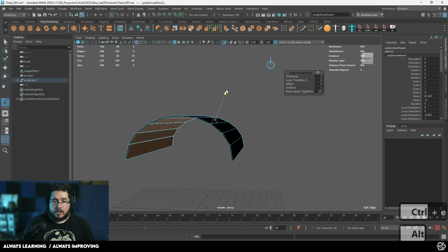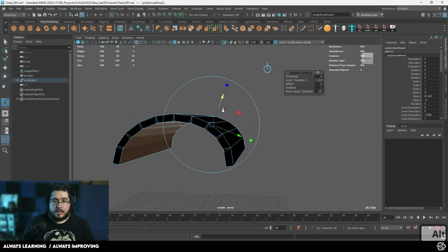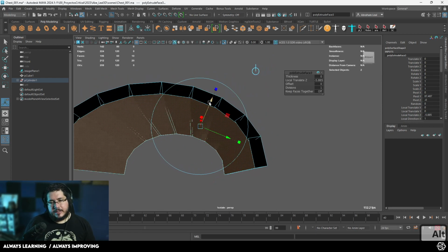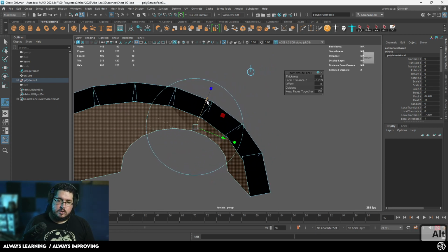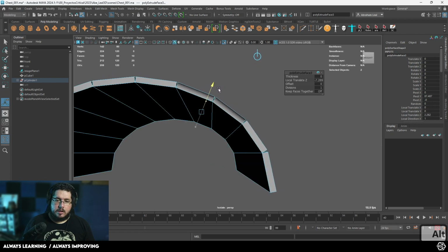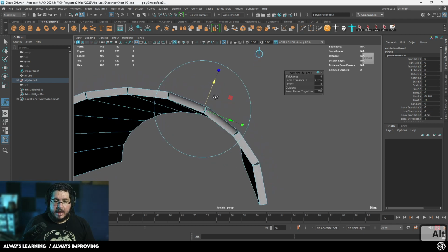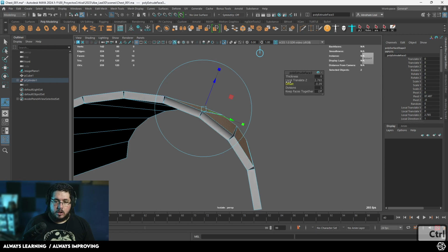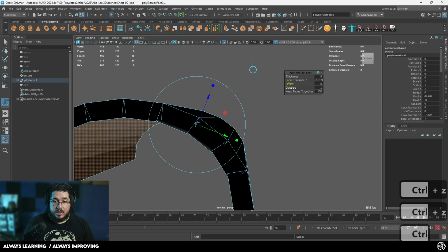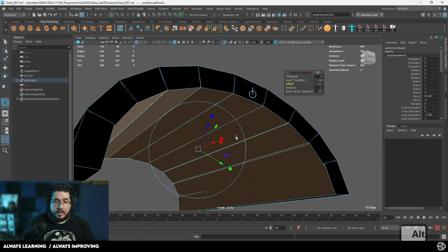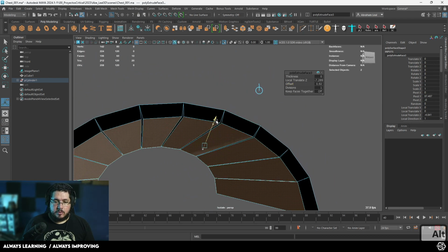That way, as you can see, when we extrude, we're going to be able to extrude the planks a little bit better. Now, in this case, they're not extruding perfectly fine. You can still see the little bit of an error right there. One thing that we can do is push them out like this, and then offset out a little bit so they match. They're a little bit closer. I think this is good. Another option is we can push them in and then use negative offset to taper them in. Both of those options are perfectly fine.